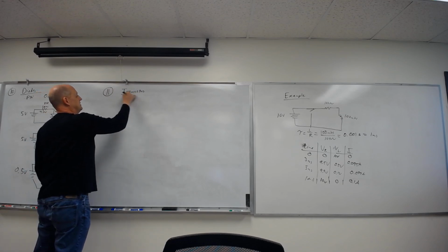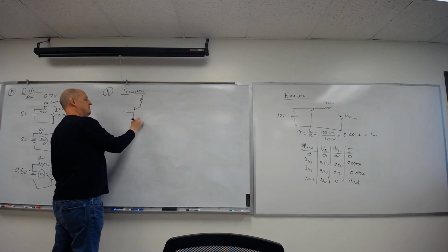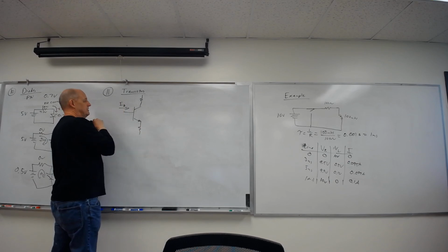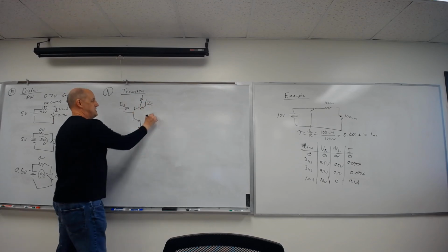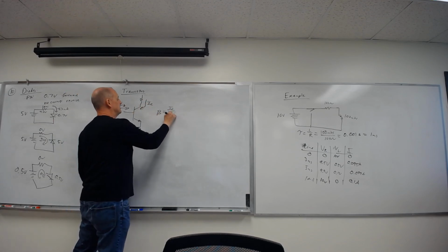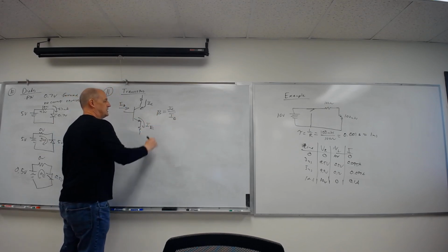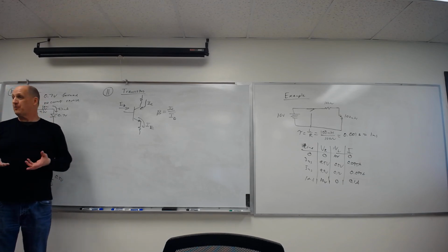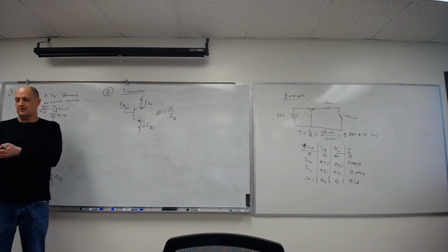Transistors. So that's the one where I made you go through in the lab. And I said, hey, we're going to measure this current in, and we're going to measure this current. We use voltages, Ohm's law. And then beta is equal to the collector current over the base current. So this is basically week one, the first week of transistors: how do they work? I had a whole series of homework problems in there where you measured, calculated voltages and currents. That one is totally fair game for the test.